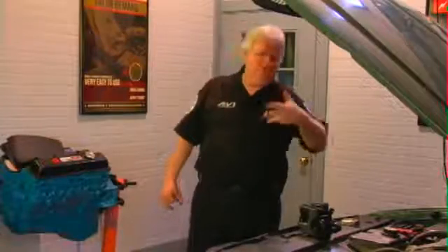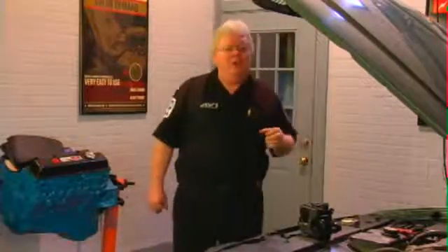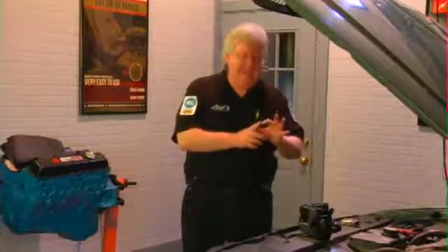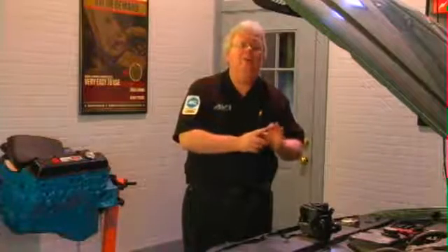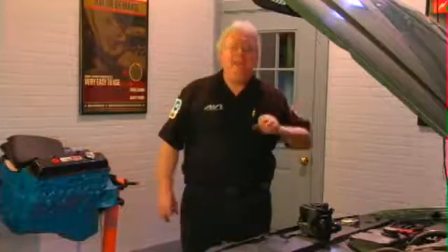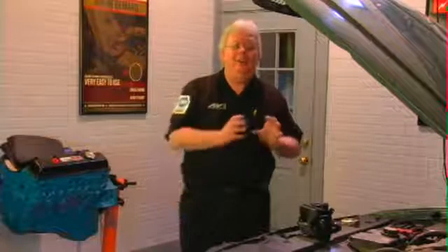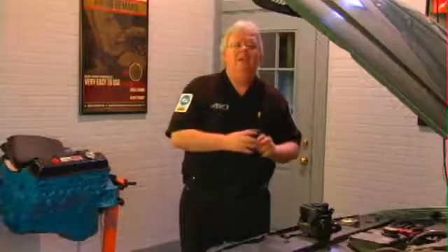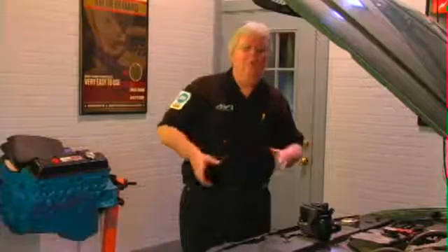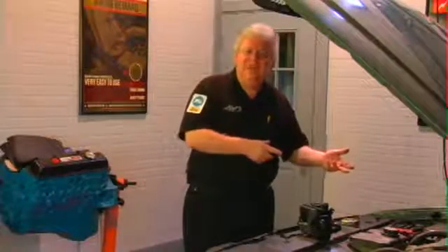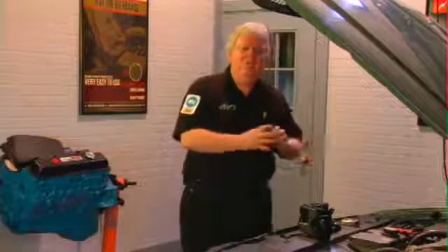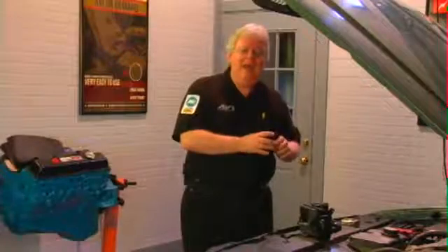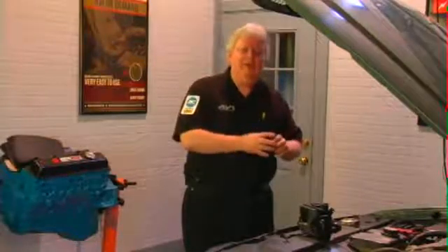On other vehicles, and General Motors is the other example I'll use, they don't vary the pressure through a solenoid on the pump. They put a coil, a magnetic coil, around the pinion gear of the rack and pinion systems. And so now we can assist the turning with a permanent core and a field around that core. We can assist the turning along with hydraulic power steering. So these systems still have power steering that's hydraulic, but we assist it or resist it depending on the field that is set up around that pinion gear unit on the rack and pinion system.